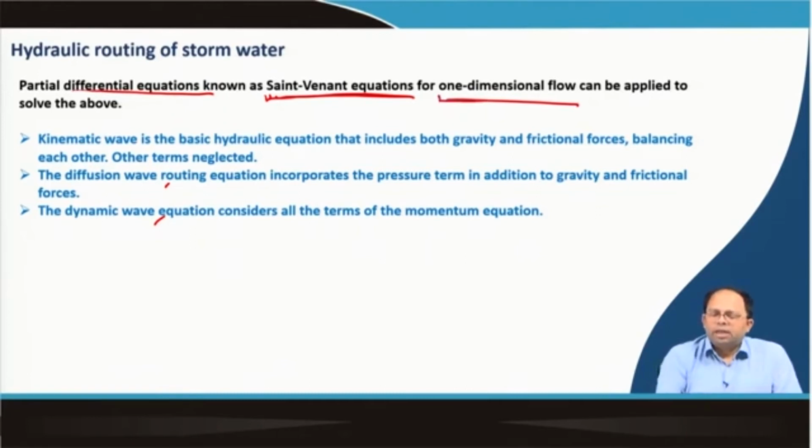So, we are usually concerned with one-dimensional flow when the water flows inside a channel. But when the water is flowing along the surface, usually it flows in multiple directions, right. For example, if there is a dike, the water gets obstructed by the dike, and once the level reaches up the dike, it will flow in all directions, right. So, that is a two-dimensional flow. The flow of water over land could be either one-dimensional or two-dimensional, but usually we will talk about one-dimensional flow. But when we model storm flood modeling, we will consider two-dimensional flow as well. That I will show you in the final module.